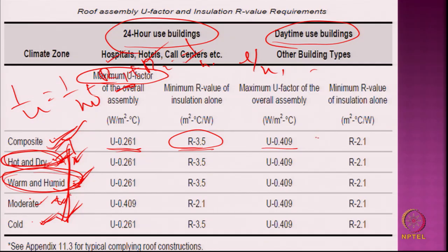So, therefore, for various climatic conditions, they have specified these R values, and they have maximum U values. So, if you just check yours, and if it satisfies, fine.